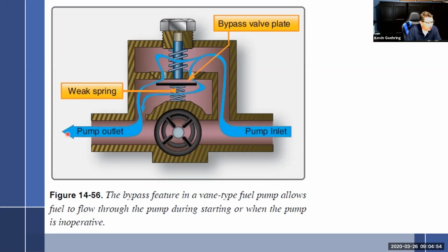The only one I'm aware of is the Skymasters that we actually have outside have a manual primer and a fuel injection system. I love them because it makes life so much easier. But otherwise, you actually prime the engine off of the fuel injection system. And so it takes a pretty deep understanding of how the fuel injection system works to not destroy the engine and actually get it off and running.